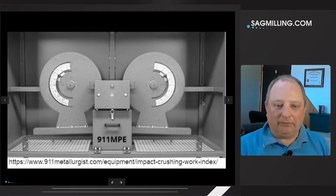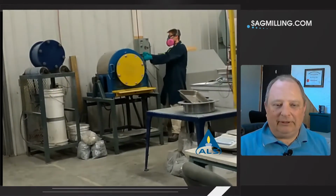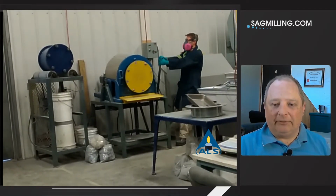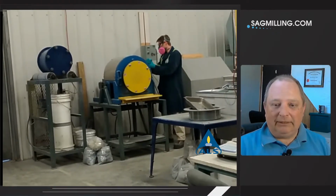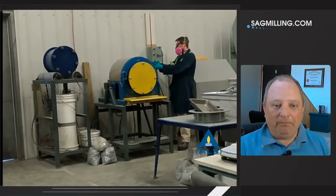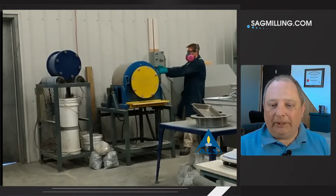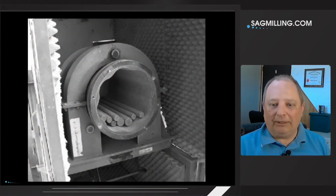bond type models. And this is a test rig for the Bond Rod Mill Work Index test. It operates in the medium size class and is generally used to give you the breakage characteristics of, in the case of our brecciated particle, separating that brecciated particle out and breaking those brecciated particles. In a non-brecciated particle, it's really used to give you what the matrix competence of the rock is, pulling apart those individual grains that you would see in an example rock.